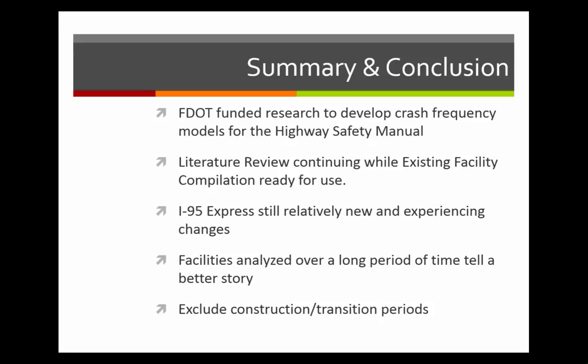And so the idea here is, should these construction and transition periods that I analyzed in the I-95 be excluded? And the answer is yes, probably, because that's not the norm. When these managed facilities are operating over the long term, they're not going to be undergoing construction and having these construction-caused spikes in crash frequencies.